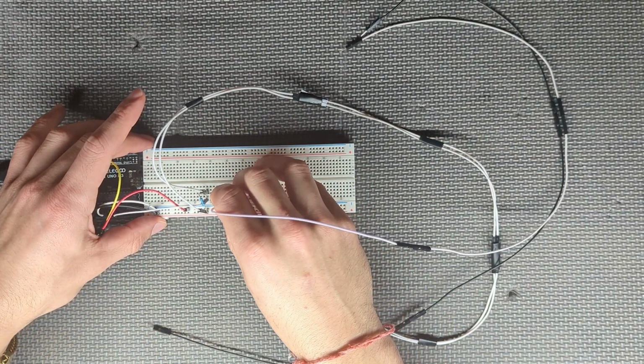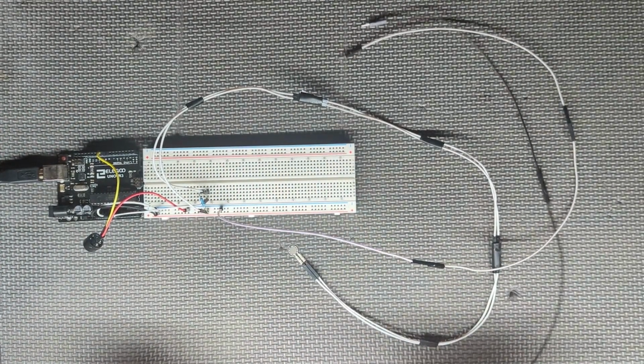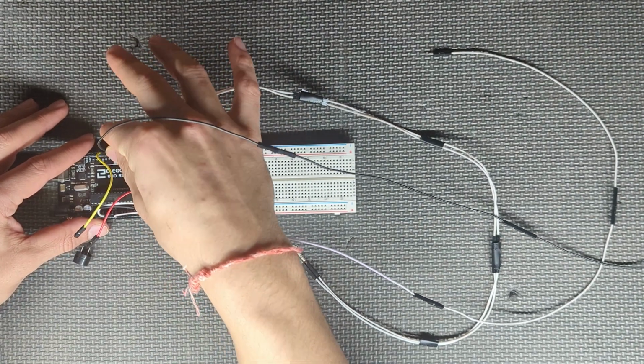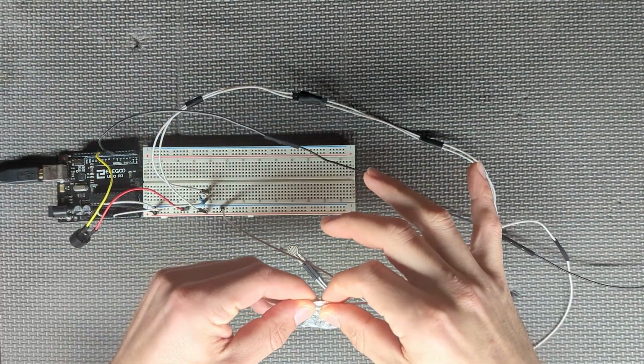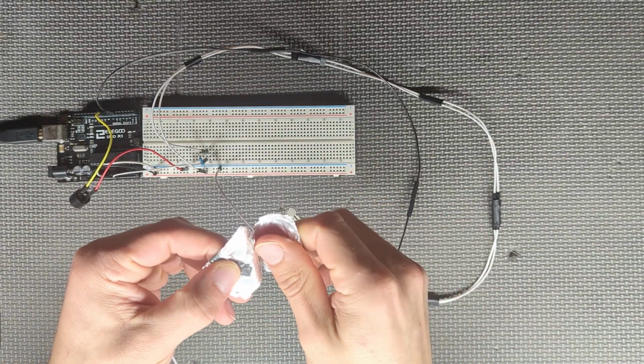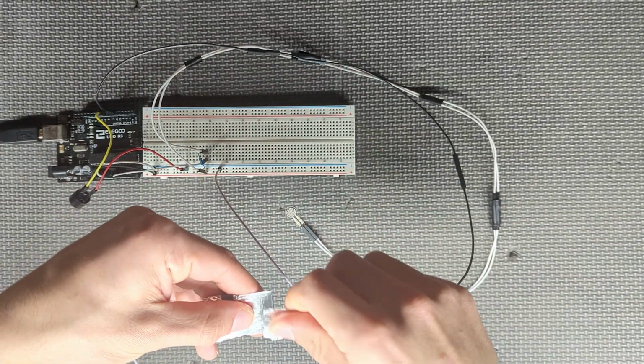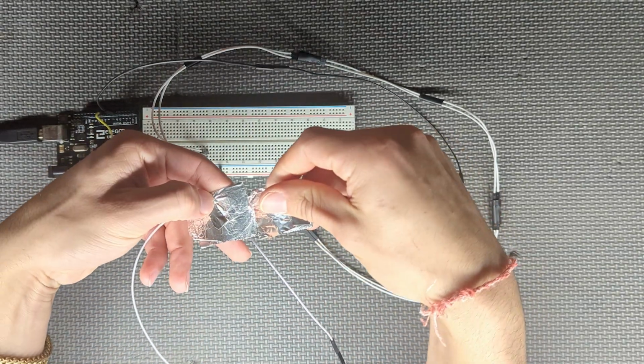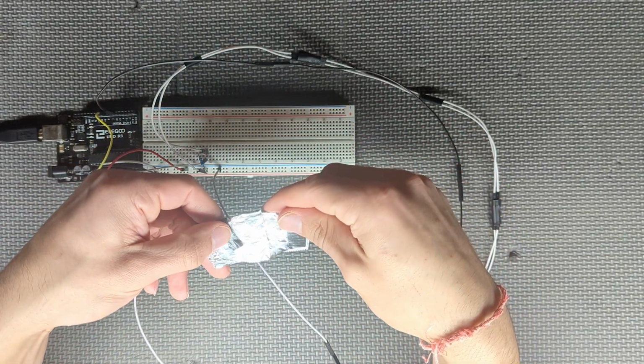The switch is simply two wires, one connected to ground and one connected to a digital pin on the Arduino. Both of these end in squares of aluminum foil, which is conductive. I can wrap the ends of the wire in the foil to increase the effective surface area of the wires, allowing for more reliable detection of when the lid is actually up.